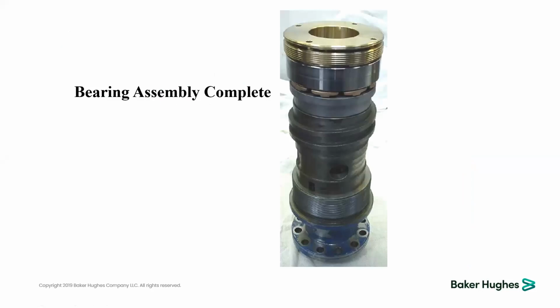So the bag section will be installed in applications when we have deviation, when we have high temperature. In reality, the seal section in industry comes in most cases with 3 chambers. So the ESP providers have multiple designs for the seal section, for example, one labyrinth at the top and 2 bags in the middle and the bottom.